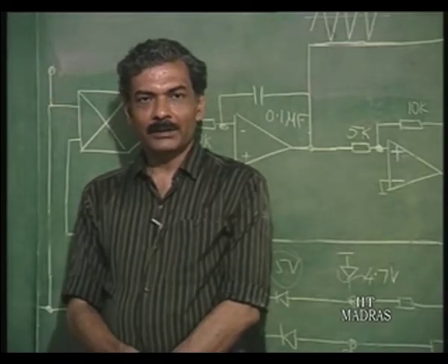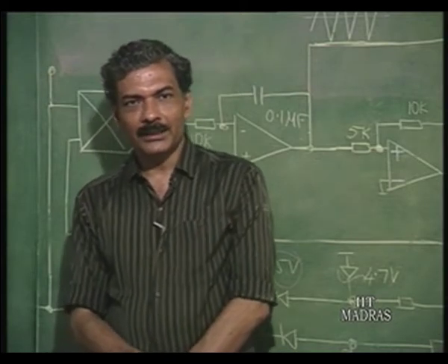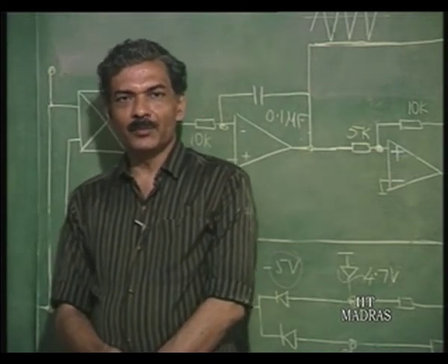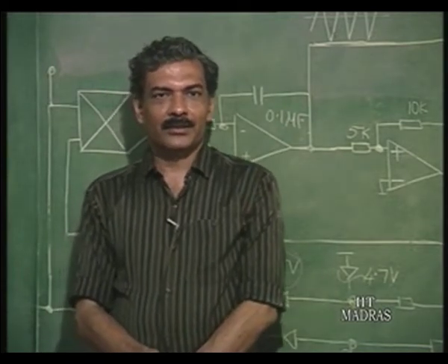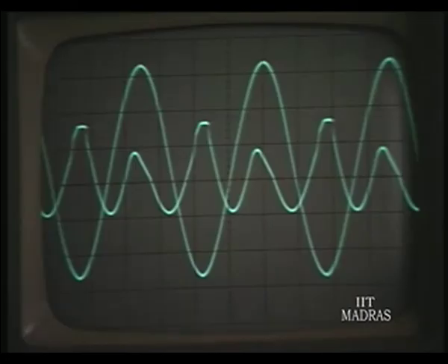Now, without the modulation, okay, you can see the output of the multiplier when the phase lock loop input as well as the AM input both are given to the multiplier. Okay. You get omega c into omega c, that is twice omega c, okay, sin omega ct into sin omega ct, sin squared omega ct, which will be containing 2 omega c component there. So, there is no modulation now.